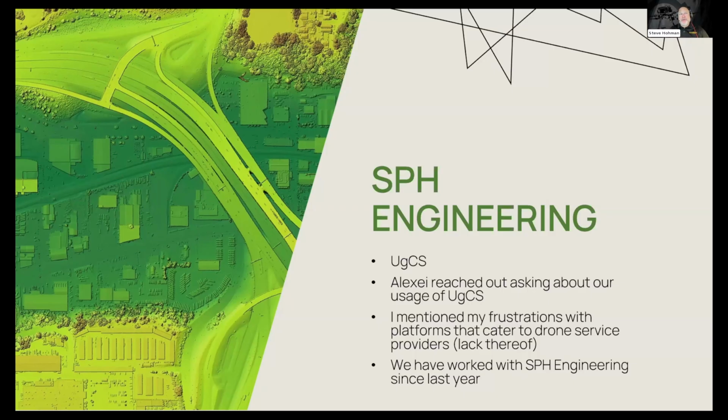If you're familiar with the DJI Terra platform, which in my opinion does a great job on orthomosaics and models, we process there as often as we can because it does a really good job. When you want to generate a grid of points, which is one of the deliverables my clients want, it has a hard limit of 10 meters. Well, my clients want 50 feet.